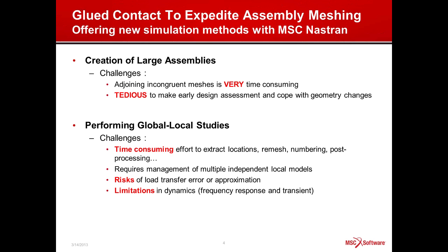So if you are of the traditional type of doing global local with different models, you know that you have to map or transform the loads at the boundaries of that coarse defined mesh. And for each load case, you have to be extremely careful on how you transfer the load, make sure you have the equilibrium maintained, and also make sure that the orientations of the force and loads or displacement-based field are accurate. And that can be cumbersome to some extent.